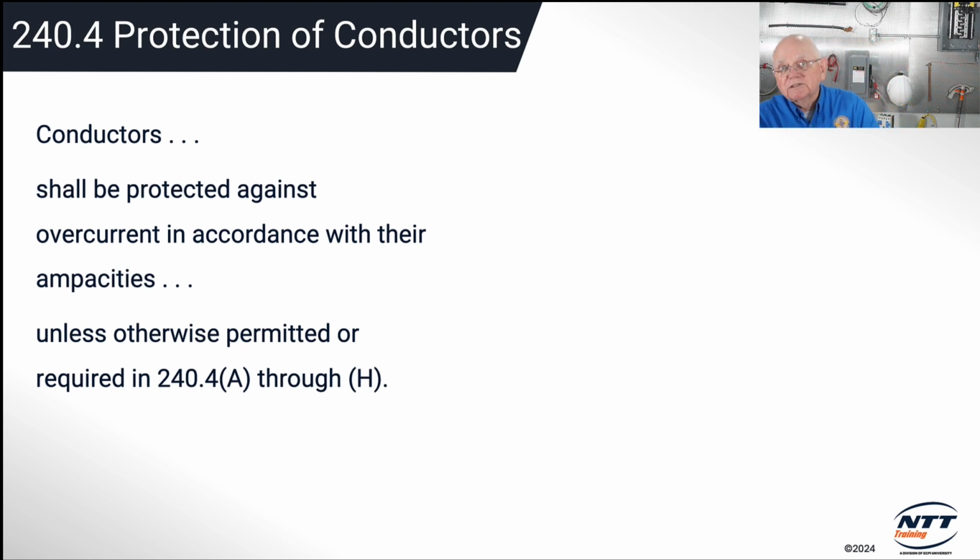If I were to take and just disconnect that black energized wire for some stupid unsafe reason again, while it's energized, and take it somewhere in that condenser unit, touch it to the frame of that condenser unit, bam, I'm going to get a large amount of current flow because the frame of that condenser unit is all connected back through my equipment grounding conductor, right, and back to my neutral at the main panel board. So I get maximum current flow most likely once again, and immediately, instantaneously, that breaker is going to trip. So it's going to protect me. That breaker protects me for short circuit and ground fault conditions. It does not protect me for overload.